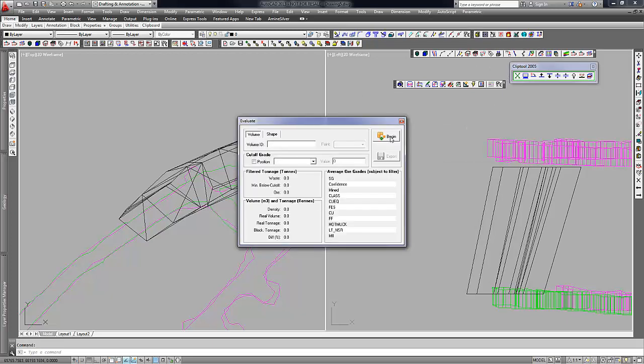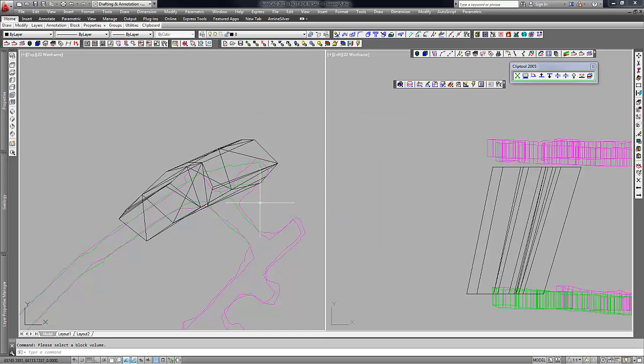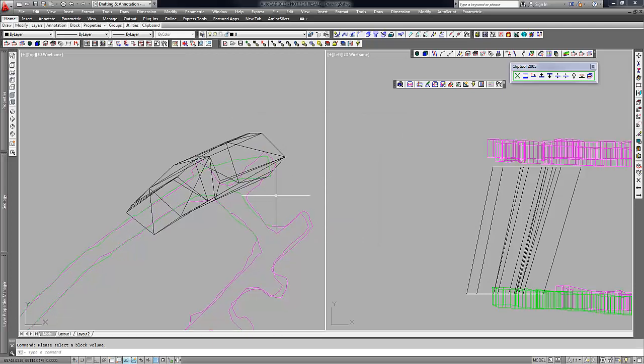Now I'm just going to quickly query it. I'm not using a cutoff, I'm just going to grab it like so. So in this case, I'm getting 38,000, almost 39,000 tons of ore, of mineralization, and it's grading at about 3% copper equivalent. So now that I've done that, I can now use this shape to build my drill blast sequence. So I'm done with my stope for now.